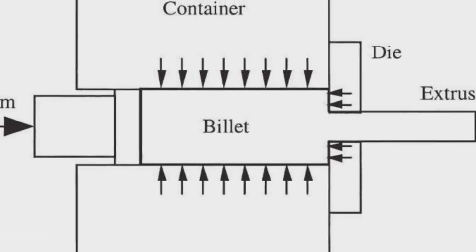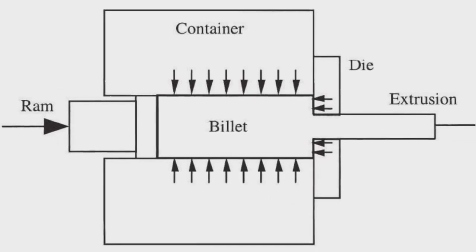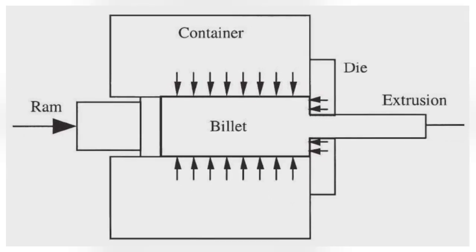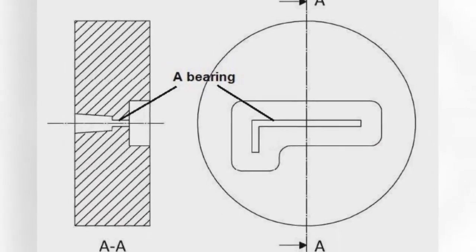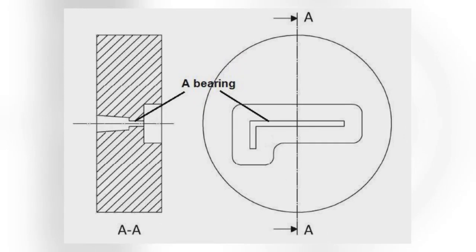Now, aluminium extrusion is a plastic deformation process in which an aluminium billet is forced to flow by compression through the die opening. This opening is a much smaller cross-sectional area than that of the billet. The extrusion die can have different designs: solid, hollow, or semi-hollow, each affecting how the aluminium is shaped during its